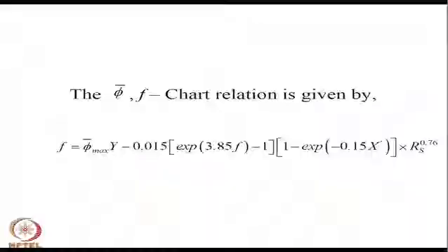The whole idea is, assuming that this correlation is valid, rather the correlation may not know where that number phibar max is coming from. It may be from a south facing surface or a non south facing surface. So, if you have a method to calculate the monthly average daily utilizability for concentrating collectors or non south facing flat plate collectors, perhaps the same correlation can be utilized using your phibar max as the appropriate phibar.